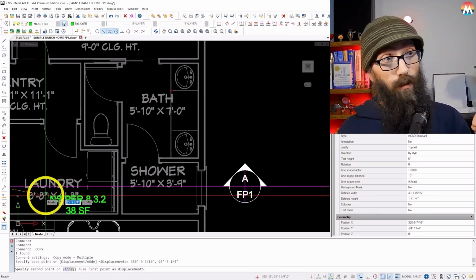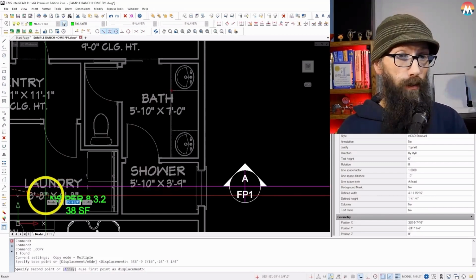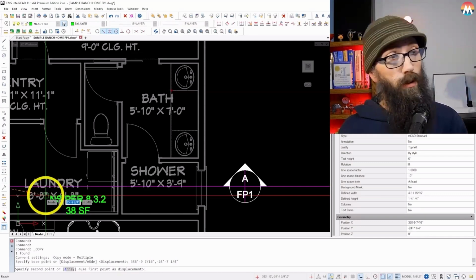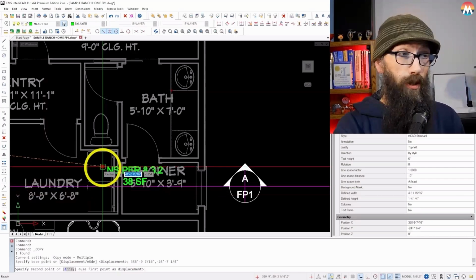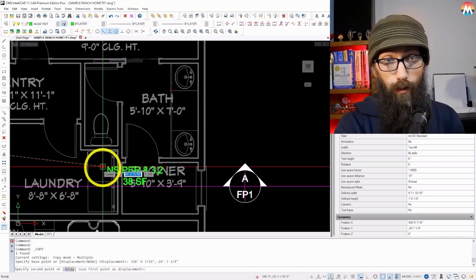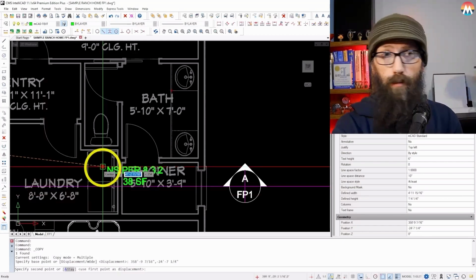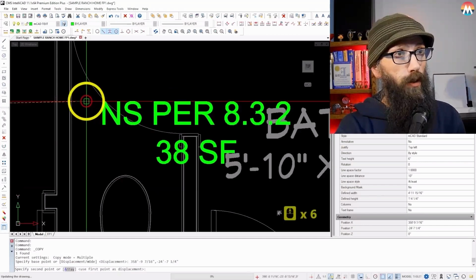And the way that this is broken up, we're going to have 3 rooms under 55 square feet. But I think if they weren't broken up the way that they are, it would be big enough to require a sprinkler. So it's kind of an interesting situation. Even if the room, like the code specifically says, even if there's only a toilet, it's still a bathroom. So that would be talking about this area right here.